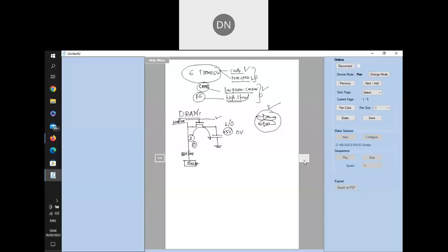But it's very good. You require only one transistor, the space required is very less and the cost is also less, because instead of 4 transistors being required, it is divided by 4. So if 100 rupees is required there, only 25 rupees is sufficient to design one DRAM cell. But what is the disadvantage here? What are the challenges here?